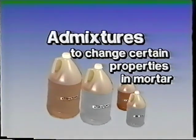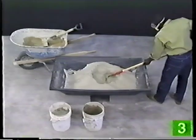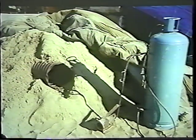Sometimes admixtures are considered for use in mortar to change certain properties or for the ability to build during cold weather. In most cases, admixtures are not helpful to the performance of the masonry and in some cases hurt performance. There are alternatives to using admixtures. For example, to increase workability, use a wetter mortar or slightly increase the proportion of fine sand in the mix. For cold weather construction, heat the sand or water instead of using an admixture.